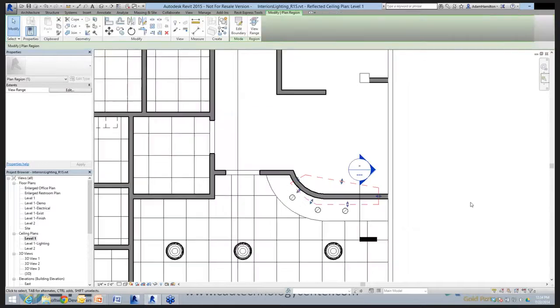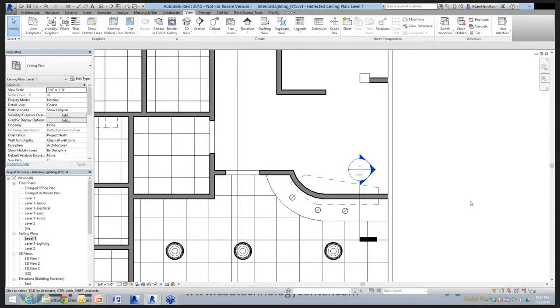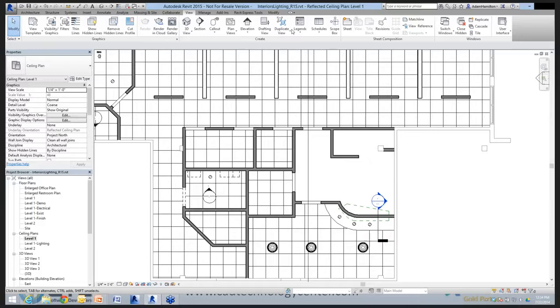And here we now do not see that opening in this view, whereas the rest of the model is still affected by the main global cut plane. So that happens to be, again, on the View tab, Plan Views, the drop-down Plan Regions. It's a very important element that few people actually use or use effectively that we get requested information about. Okay.